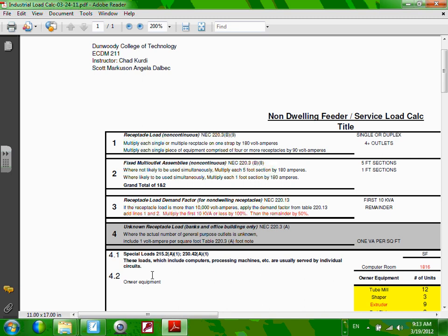You grab one big fat bus duct with copper, you pass it right at the top of you guys here, and you take a cord and you tie it to every single machine. That bus duct needs to be sized. Is it a 200 amp bus duct, a 400 amp bus duct? That's what I mean by the bus duct. So how are you going to size it then? You're going to size it based on the loads that tie to it.